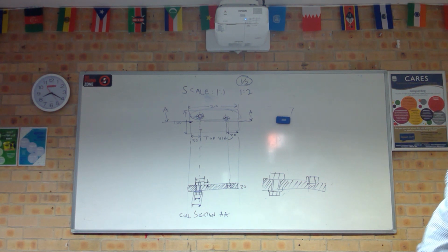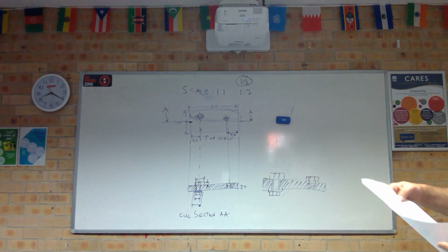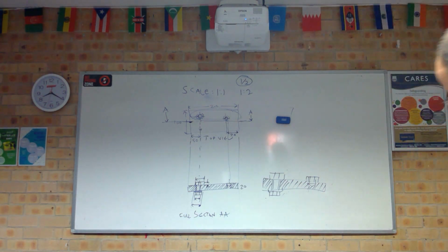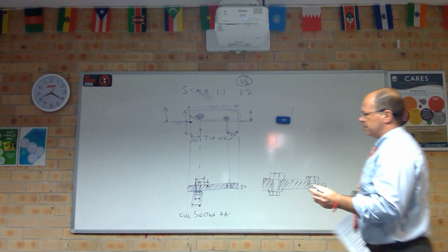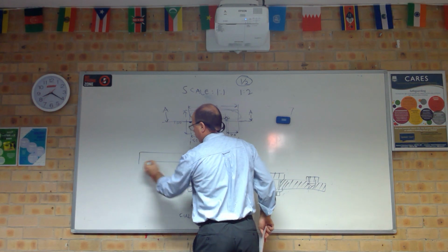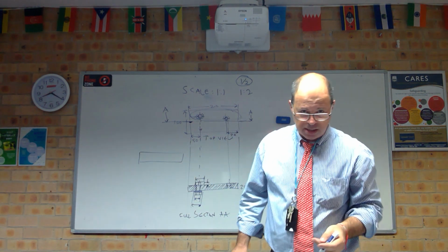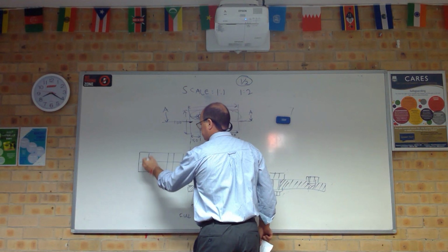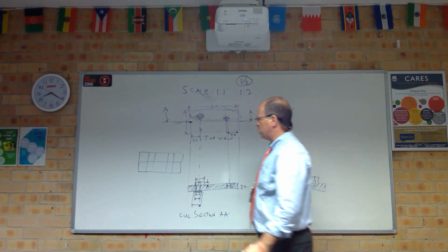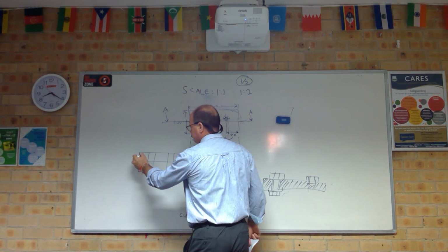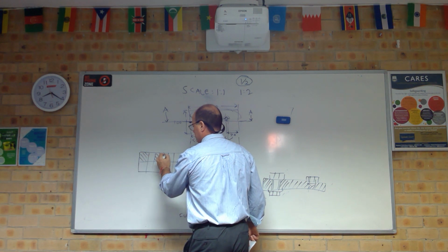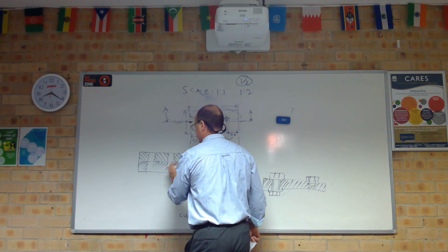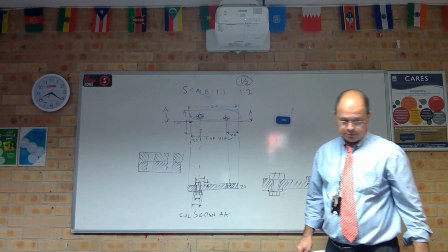And then finally, I ask you to do the whole lot again, but this time I'm asking you to take two of those steel blocks and join them together. Now the only thing you need to know about that, okay, is that when you have two materials, all the through holes, all the stuff that I'm asking you to do is exactly the same. But if you're joining two materials with holes, okay, first thing you need to know is that if this material is different to the one below, when you hatch, you need to hatch in the opposite direction. Okay, that's one thing you need to know.